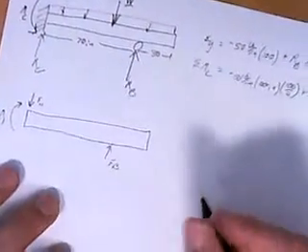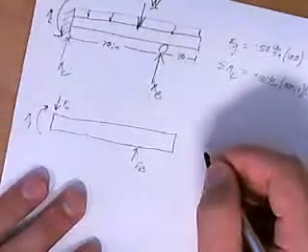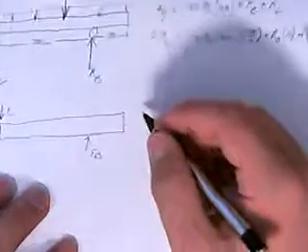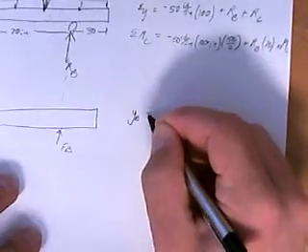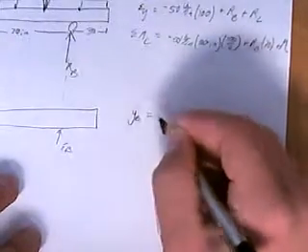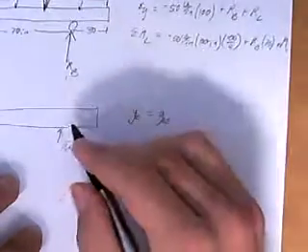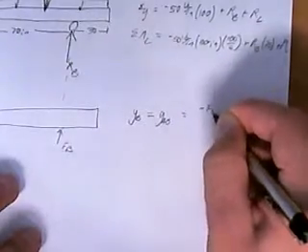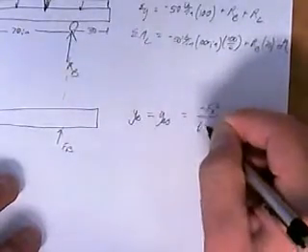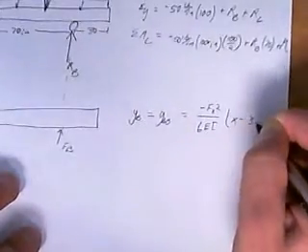If you're looking at the back of your book, what we're going to use are the displacement equations from the superposition principles. That equation is YB, I'm actually going to call this YAB, because we're going to have to do this twice at the same location, is equal to negative Fx squared over 6EI times (x minus 3a).